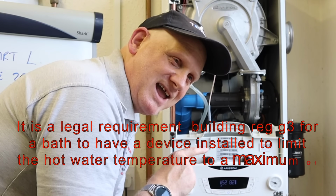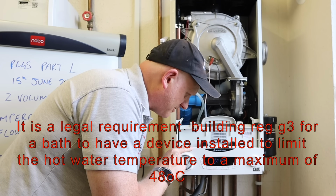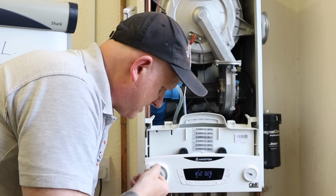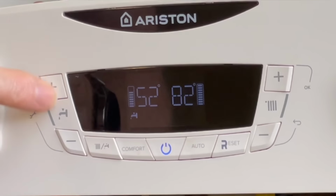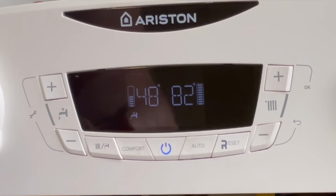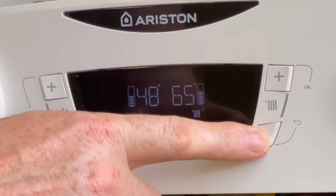But if you can get in a bath without putting cold water in, then you've set the water to the right temperature. But obviously if you need to wash the pots in your kitchen sink, then you'll need hot water to kill the bugs. Or if you've got a dishwasher, set it up from your bath temperature. So that will take a bit of altering, but the more you can adjust this temperature down, the more money you're going to save. And when it comes to the central heating one, it's just a matter of dropping it down to 55 first.